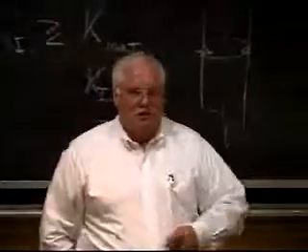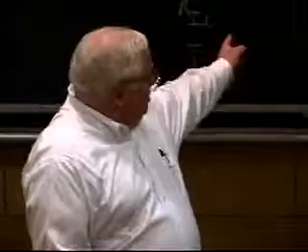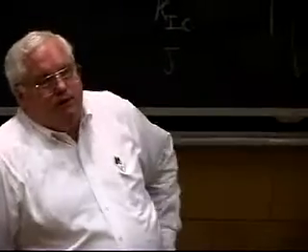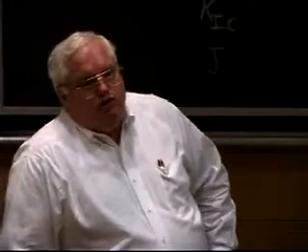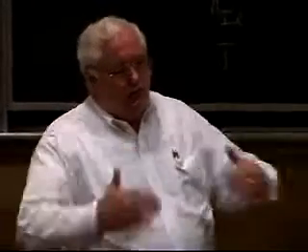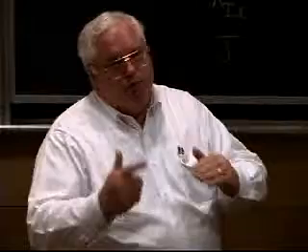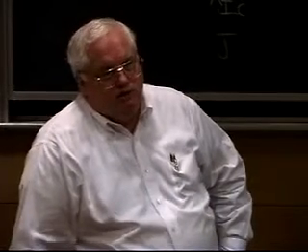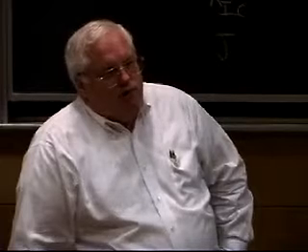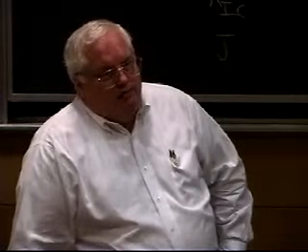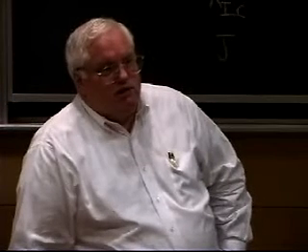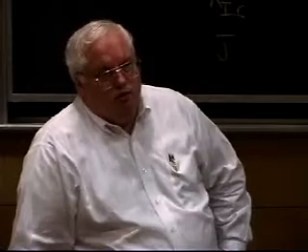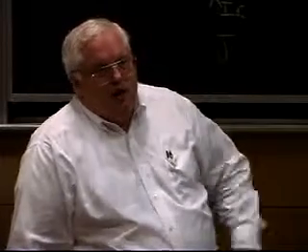Give me your question again. So you're not getting a stress out of a Charpy. You can get that kind of curve. People are still debating whether the Charpy test is the appropriate way to do it, because the J integral test should be a slow bend, not a rapid bend. And steels do fracture differently under very high strain rates than they do under low strain rates. So you don't really get a stress out of a Charpy. You can get a number that some people can argue is equivalent to a stress, but other people argue that it's not correct. Because actually what they also have is K1D,